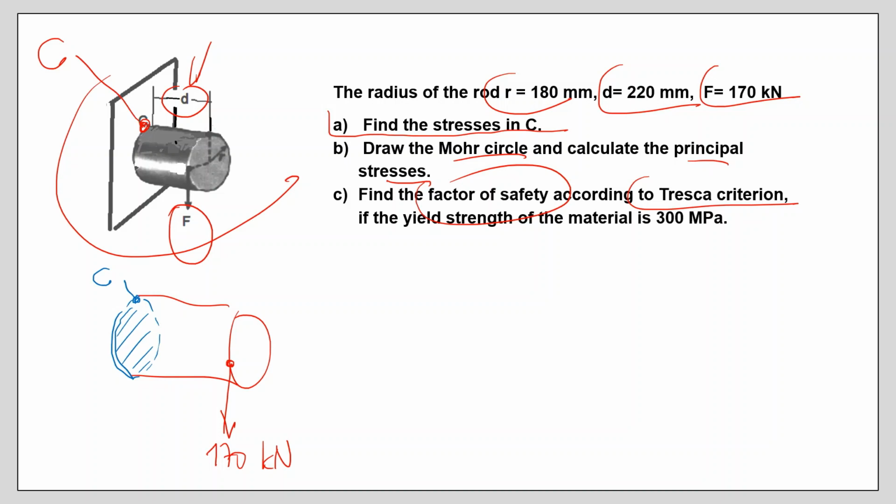In order to do it, I can write down the equilibrium equations for this free body diagram, or let us do it simpler and save some time, because my purpose in this problem is to apply the failure criterion. So in the y direction, that is this direction, you reach an equilibrium if you have a 170 kilonewton shear force in the blue section.